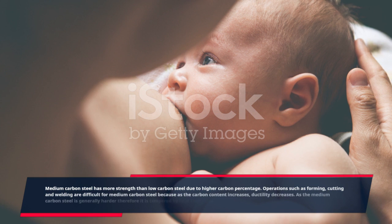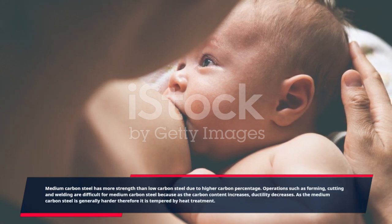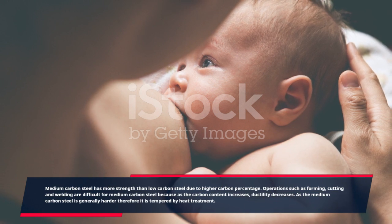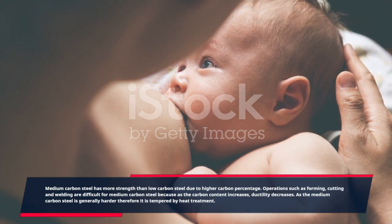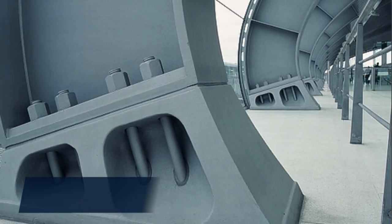Operations such as forming, cutting and welding are difficult for medium carbon steel because as the carbon content increases, ductility decreases. As the medium carbon steel is generally harder, therefore it is tempered by heat treatment.